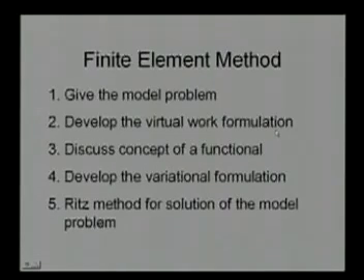After the virtual work formulation has been developed, we will also discuss another concept, the concept of a functional, and using the functional we are going to develop something called the variational formulation. We will show that, for at least this model problem of interest, both the virtual work formulation and the variational formulation are the same. Finally, we are going to take the variational formulation and develop a method called the Ritz method.